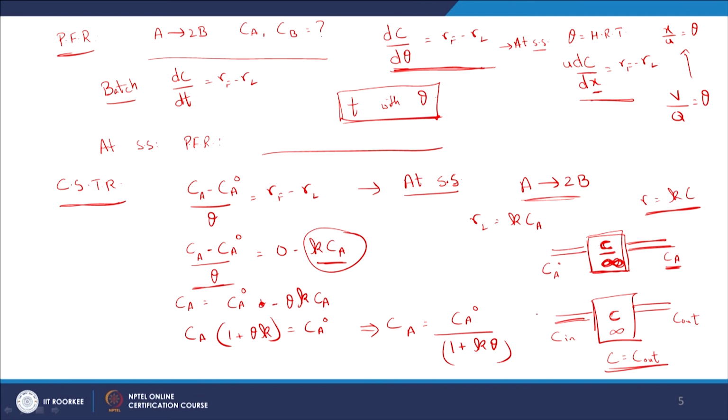Whatever is coming in is instantaneously diluted, then you have the relevant equations, and then it flows out. So in a CSTR the concentration inside the reactor and the concentration outside the reactor are the same. That is the reason why, when writing the rate of loss of this compound, we could directly write it as the concentration of A leaving the system or even within the system, which is going to be the same. So that is the aspect here.